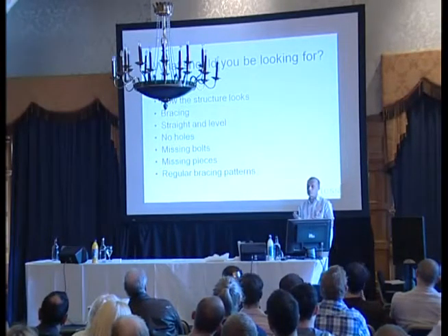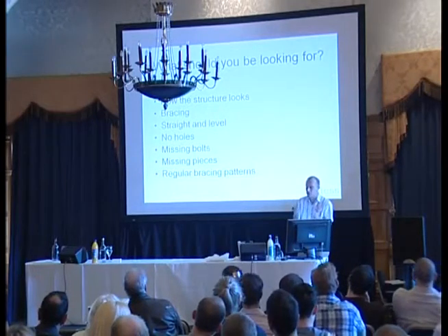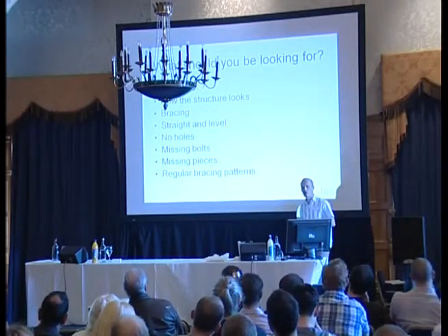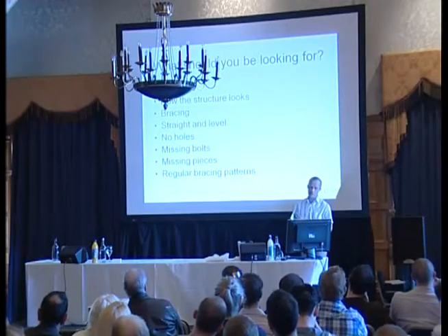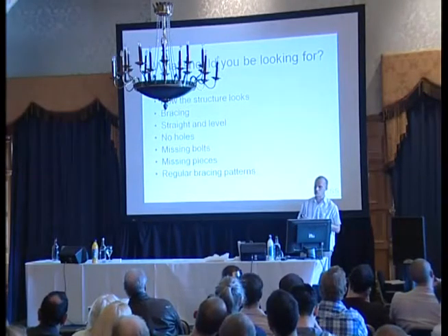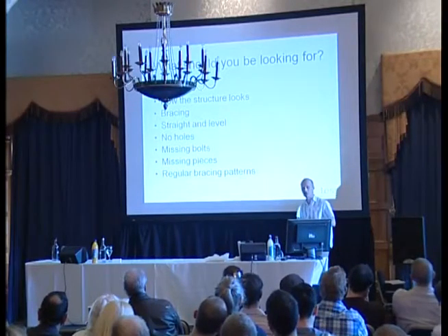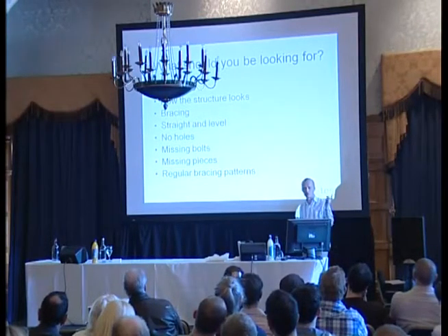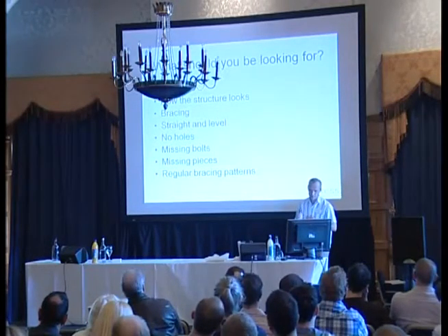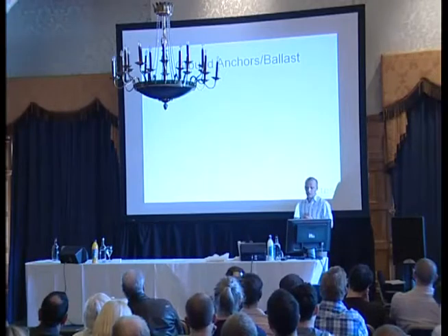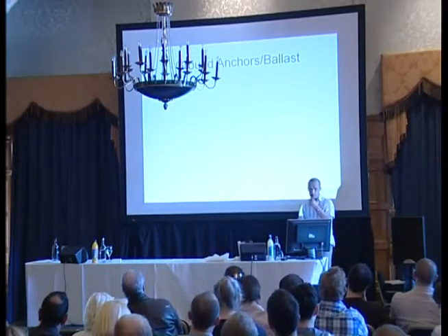If they can show you the tables to say it doesn't matter, it doesn't need to be lined up, then all very well, and you can be satisfied that that's the way. But most truss that I know, you want to line up the diagonals. The bracing should line up in a long line. If it doesn't, they've just tipped it up the wrong way. So those are the kind of things you should be looking for.